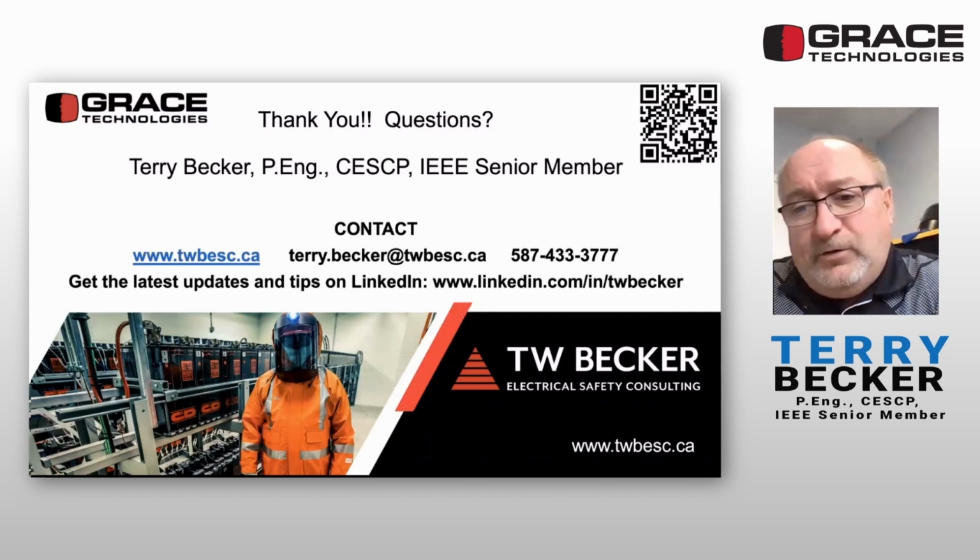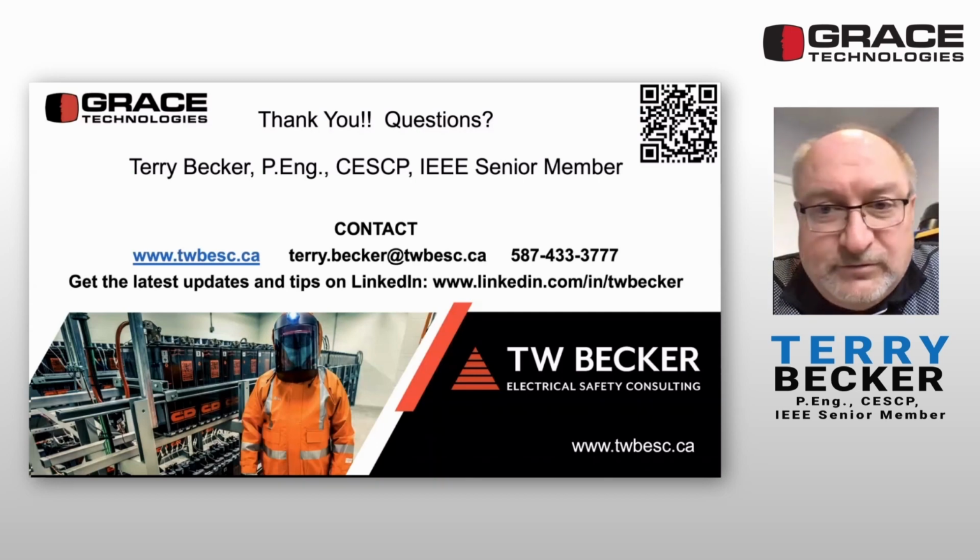But you can open up a door on energized electrical equipment. This is where you're going to hear different opinions: without any arc flash or shock PPE, to just do an inspection on the other side, or then to use an IR camera. And the person using the IR camera doesn't need arc flash or shock PPE. They stand outside restricted approach.